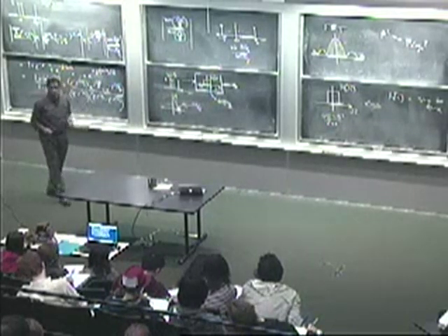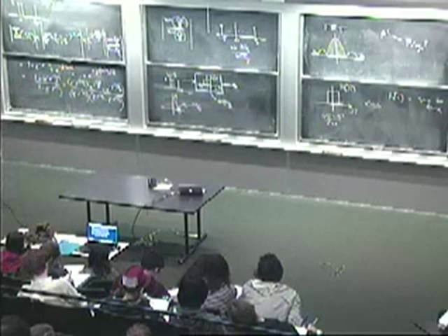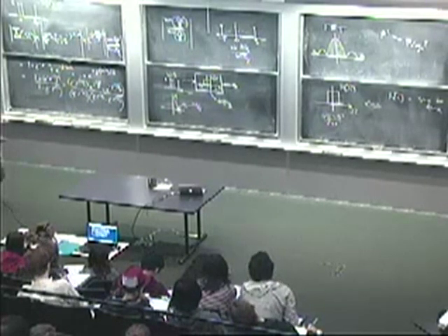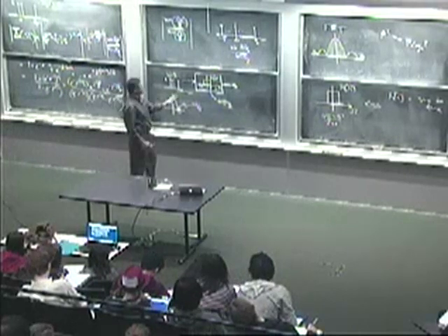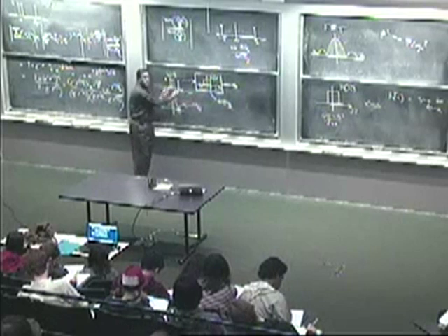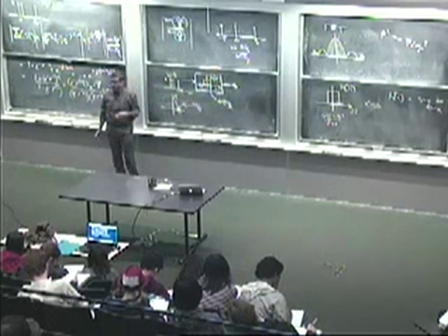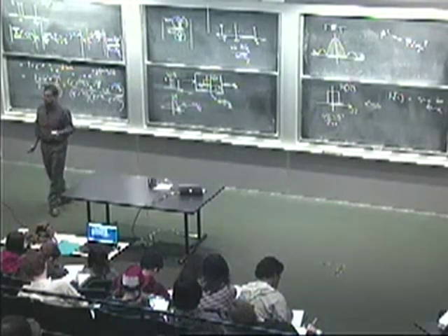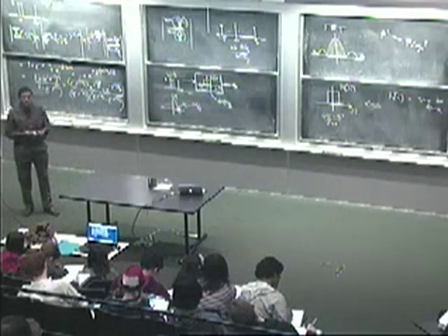Okay, and you can see that clearly. That's something you can explore in your experiment. So if you wanted to get more clearly defined output for a given low-pass channel, you might want to increase the length of your pulse. Of course, that's going to slow down your signaling rate, so there's a trade-off involved, right?